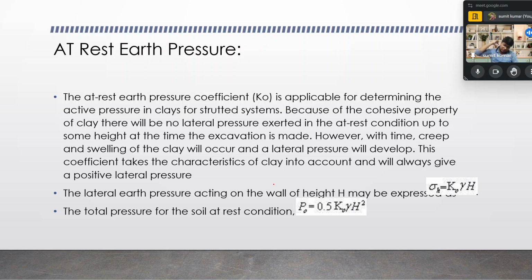See, we are talking about some important facts over here. Because of the cohesive property of clay, there will be no lateral pressure exerted in the rest condition. This is also applicable up to some height at the time the excavation is made. However, with time, the creep and swelling of the clay will occur, and a lateral pressure will develop.